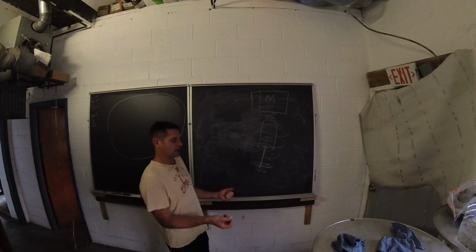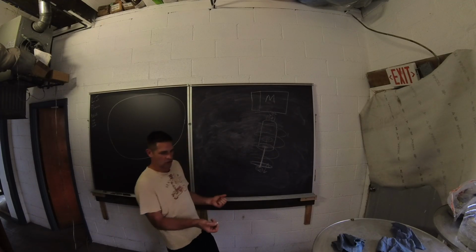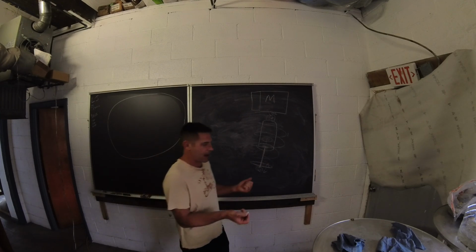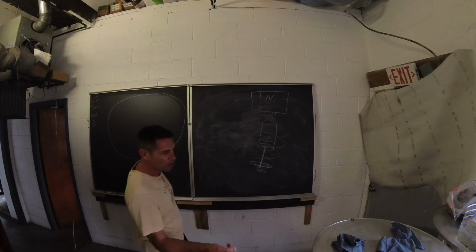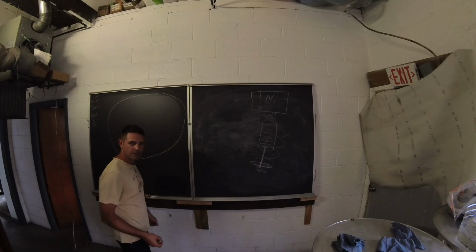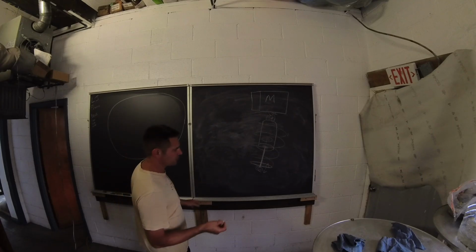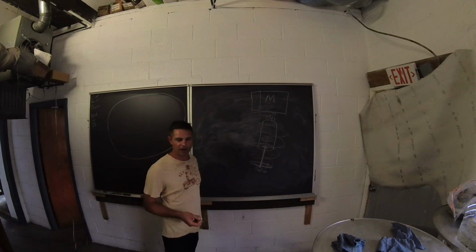It slowly comes up, and the suspension kind of gets stuck down in its travel, and it takes, you know, 2 minutes for it to slowly get back to its rest position. That's an overdamped spring mass system. Once you get into velocity and other stuff, dampers get very complicated.